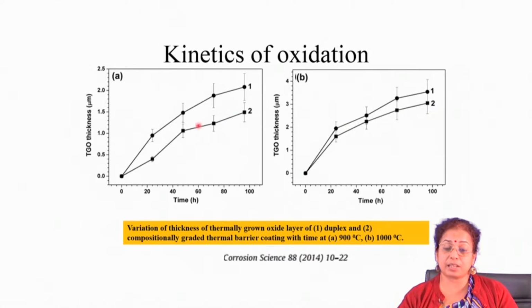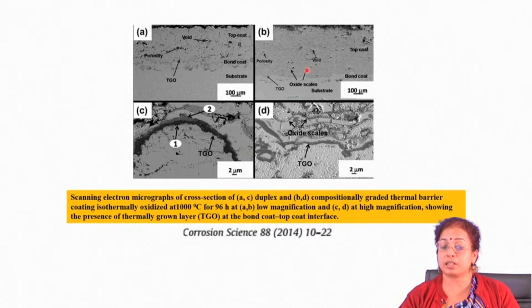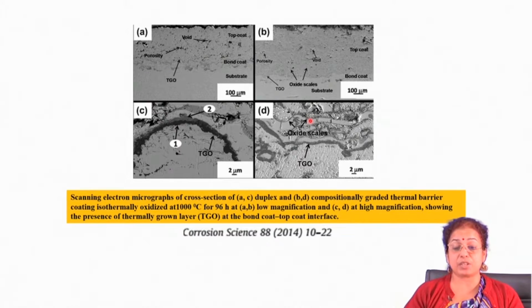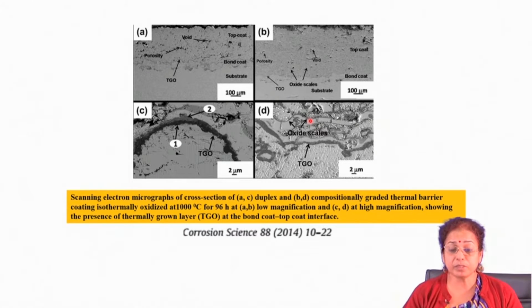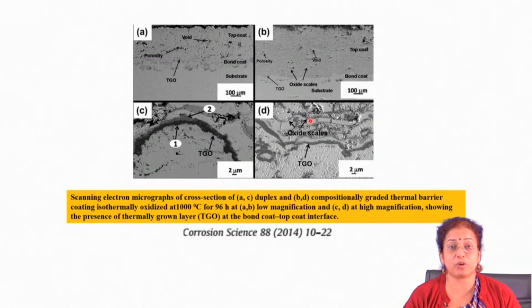So, you can understand that by the application of the graded coating, the oxidation resistance property could also be improved, which was not earlier known. The main reason is that a lot of interfaces are generated because of the intermixing and spraying of the ceramic metal mixed layer instead of having only a ceramic layer on the top. So, those interfaces play a very important role